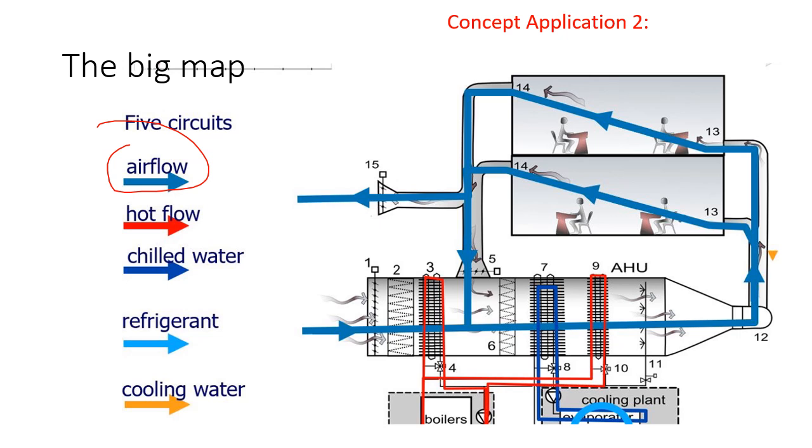And then it goes over here, where there's a reheater. Sometimes we switch it on even in summer, but in winter definitely this is on. Then air goes to another device which sprays vapor, so this is a humidifier. And then, driven by the fan, it is pushed through the ductworks into the room.